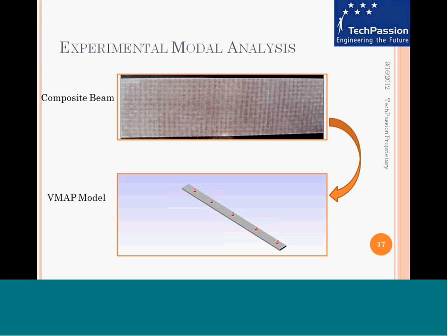And we also did modal analysis. But then to do more detailed simulation, things like transient analysis, or you apply some kind of stochastic loading on the structure and you want to characterize the fatigue life and so on, one of the key parameters that one needs to understand is damping.